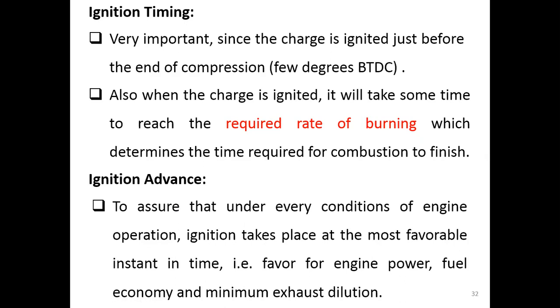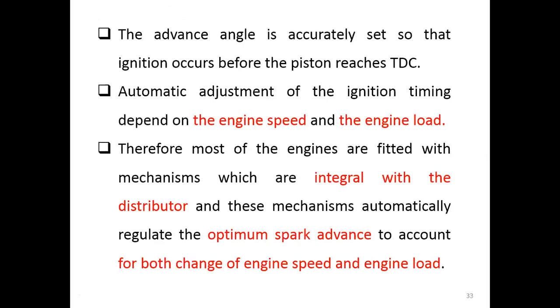It means it favors the engine power, favors the fuel economy, and gives us the minimum exhaust dilution. So this is the thing that we want to happen, and that's the reason why we have to do the ignition advance. The advance angle has to be accurately set so that the ignition occurs before the piston reaches the top dead center.